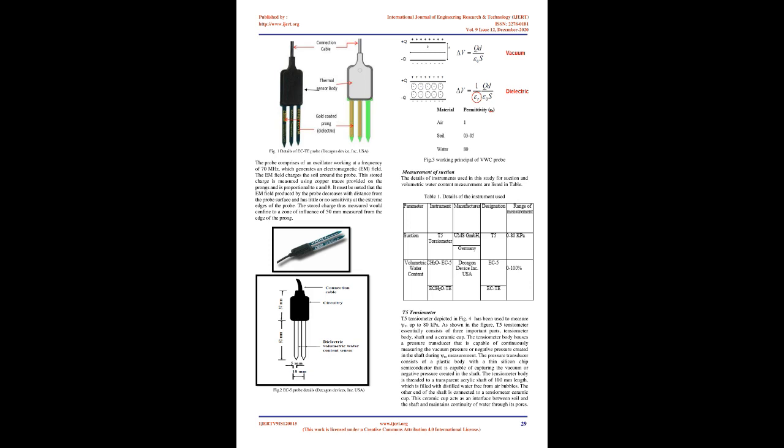Details and basic concepts of these instruments are discussed as follows: an ACT-ECTE, designated as ECTE, and an ACT-EC5, designated as EC5, are capacitance type probes, as depicted in Fig. 1 and 2, respectively. They measure based on the dielectric constant or permittivity of the material in which they are inserted. EC5 is two-pronged, whereas ECTE is a three-pronged probe. ECTE measures bulk electrical conductivity and temperature in addition. The prongs are made of epoxy-impregnated fiberglass, circuit board material. It must be specifically noted that the probe averages over the entire length of the prongs.